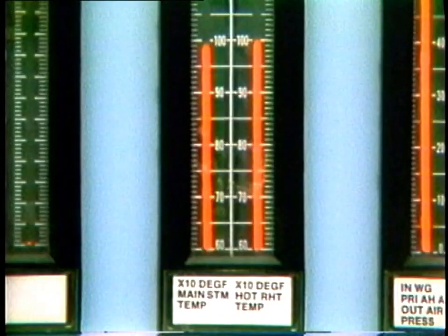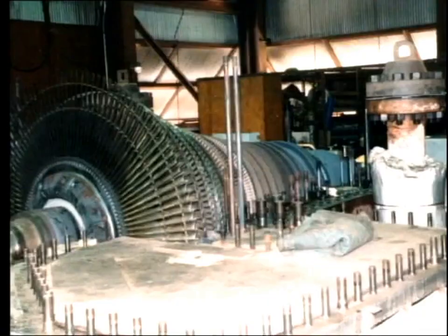An important feature that must be borne in mind is the effect of temperature upon the turbine internals and associated pipework. When we consider that the temperature of the steam entering the turbine is, say, 900 to 1,000 degrees Fahrenheit, it is apparent that its effect upon the metallic components is to cause a considerable expansion. Now, if all the components were to expand at the same rate, this could be accommodated. But this ideal situation is not easy to achieve.